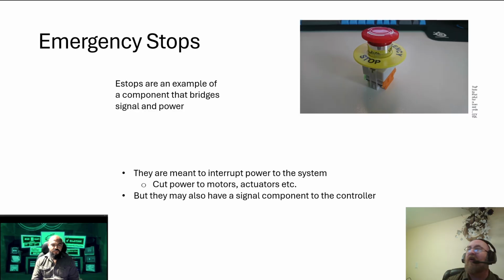However, for the rest of it, you don't want to have the e-stop shut down the PLC, because then it means you have to reboot the PLC to do anything with the system. You want power to continue to flow to certain parts of the system and not others.